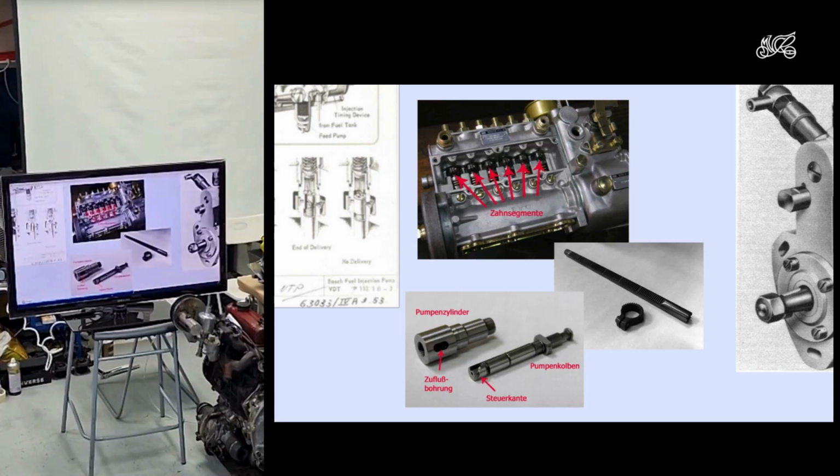So if you can imagine, the way it works is each injection pulse is initially full fuel, and then you bleed off the fuel based upon the manifold pressure to inject just a little bit for high manifold pressure, low manifold pressure. Diesel engines do the same.